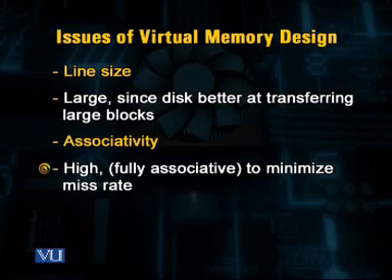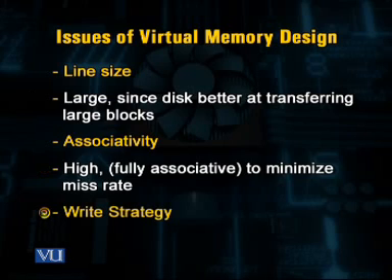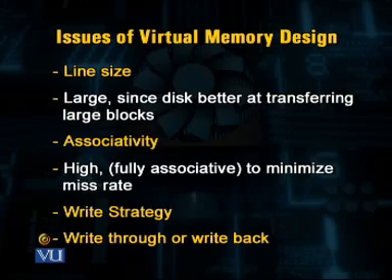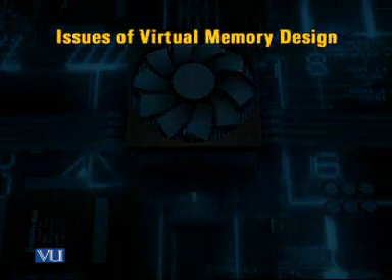And this method basically reduces the miss rate. Furthermore, we have to find out what should be the right strategy. The right strategy should be either write through or write back. We usually prefer write back because we cannot afford to perform small writes to the disk, as miss penalty to write on the magnetic media is very high.